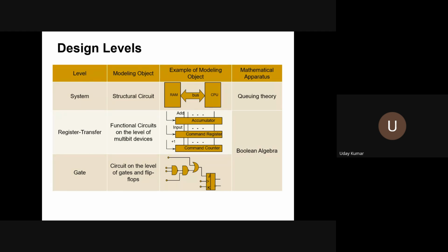For example, if it is a DSP chip, let us say you want to implement image recognition hardware on a chip. So what is the logic that you need to write? Let us say you're using a fully connected neural network, then it would be an algo core, where you'll be writing the logic in the RTL to implement the FCNN, and then the outputs and the inputs that require on-chip memory.